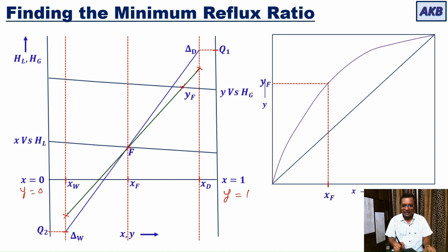So this tie line is giving the highest location for delta D, in the case where the tie line coincides with the construction line. So this will be the highest location. All other tie lines will be intersecting below this point.